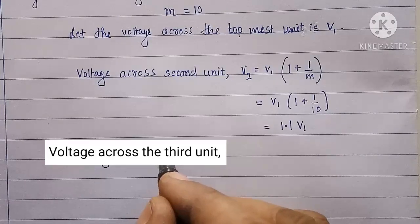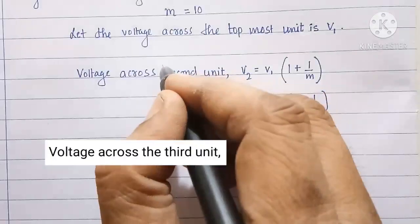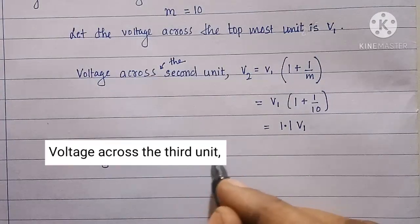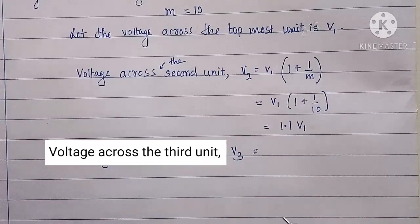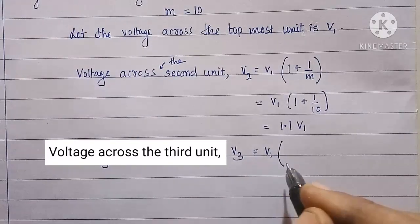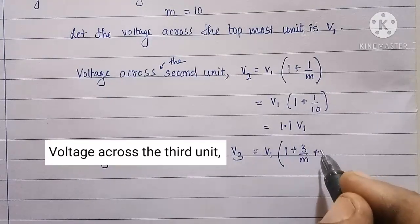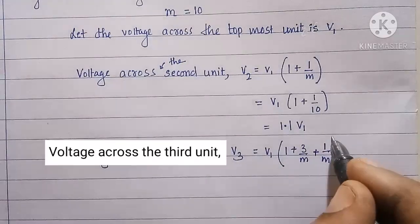Voltage across the third unit, V3, is equal to V1 into the bracket 1 plus 3 by M plus 1 by M square.